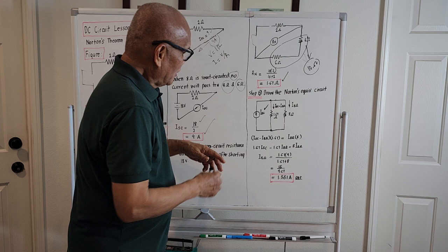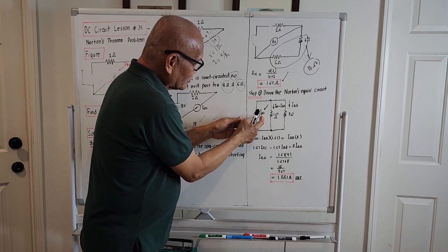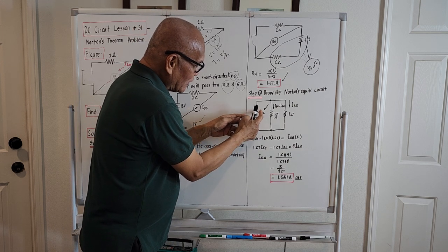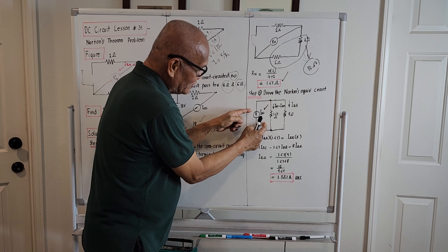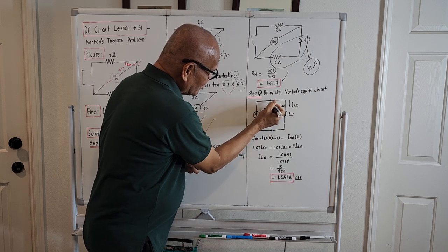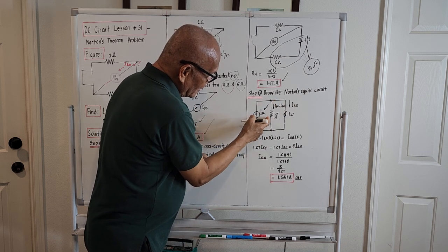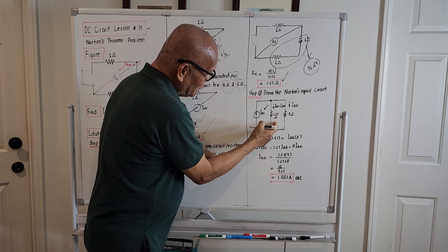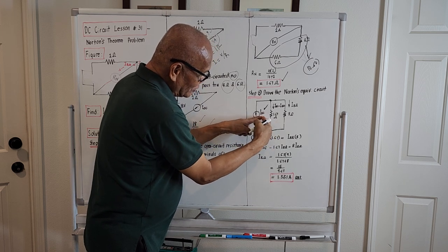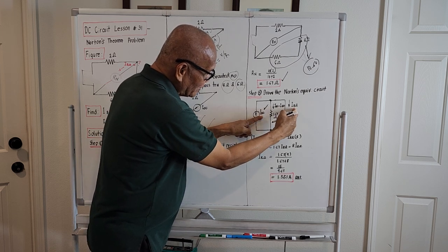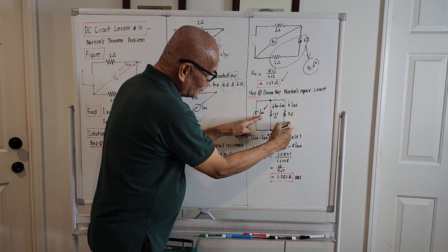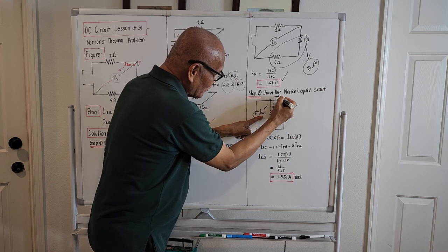If the total current coming here is the short circuit current, I with the subscript SC, considering this junction, the current entering this 1.67 will be I_SC minus the current passing through the 8 ohm load, because this is I sub 8 ohms.